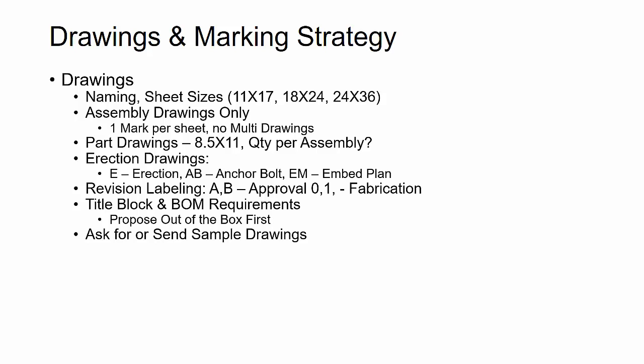And then if you can't fit something on a 24 by 36, then you start to actually scale the views down. Instead of 1 inch equals a foot, you may use 3/4 inch equals a foot or 1/2 inch equals a foot to fit more things on the sheet size or the paper.